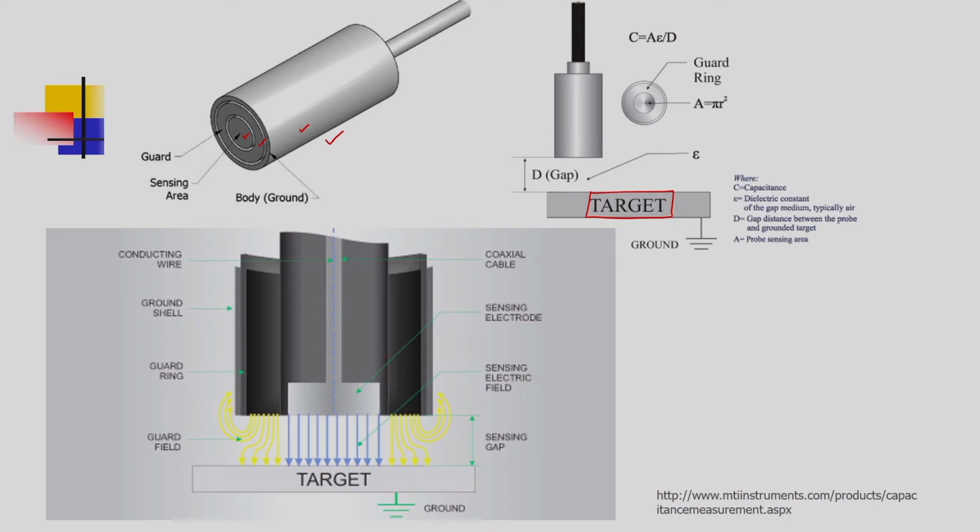Capacitive proximity switches work with a target. The only condition is that the target should be grounded. When these capacitive sensors come closer to the target, they produce signals. So, here you can see charge is applied to the coaxial cable, and when they come closer to a target, there is a change in capacitance which will be useful to generate the signal.